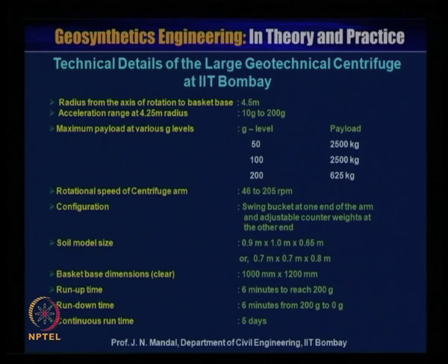The basket base clear dimension is about 1000 millimeter by 1200 millimeter, and the run up time is 6 minutes to reach 200 G, and the run down time is 6 minutes from 200 G to 0 G. It can run continuously for 5 days.